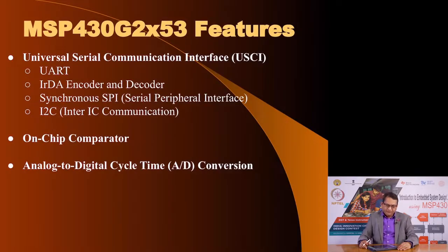For serial communication, it offers a wide variety of communication protocols. Again, looking from the point of view of one of the 6 building blocks that we discussed, there was this block regarding communication channels, and so this microcontroller offers built-in communication protocols, and the communication interface is called Universal Serial Communication Interface. It has these options. You can have a UART, which is the Universal Asynchronous Receiver and Transmitter. You could also utilize it for infrared communication, bidirectional infrared communication, IRDA.